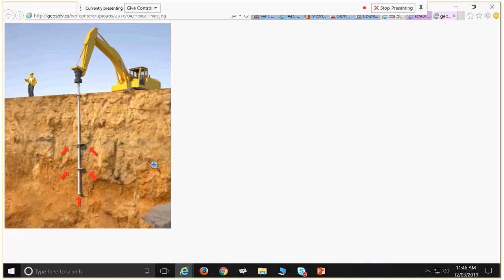So fantastic for things like that. But also, it's fairly contentious, there's varying opinions about this, you can also use screw piles and then lock them into a concrete slab as well. So your concrete slab can be locked into your earth. Problems with that are that it doesn't enable the slab to move like a raft, etc. But that is also specified by some engineers. Screw piles, slab, and lock it in place. So screw piles might be a really fantastic thing for an elevated floor as well. So once again, concrete-free alternative.